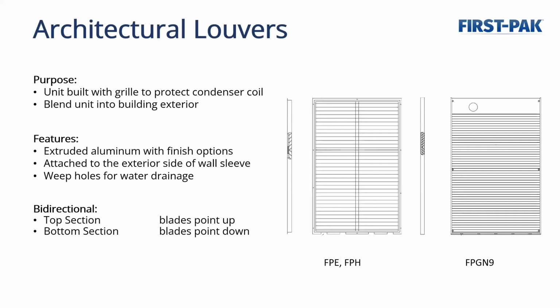The louvers on these units, so on the far right is the 95% or 96% gas unit. It does have the flue gas pipe right on the louver, so you don't have any external flue. These are what you'd call a direct vent appliance. So you need to make sure that when we're talking about these units that we ensure that the ventilation intake is separated for whatever the local code is, from that flue gas. Usually we see 6, 8, or 10 feet, something in that range. So that's the reason why we can't put the ventilation on board from the factory for these particular units.